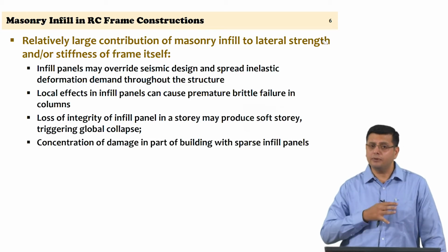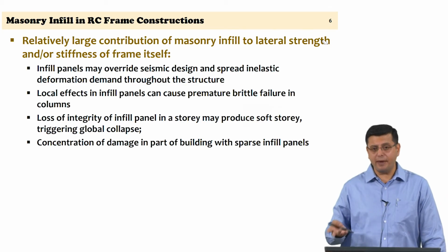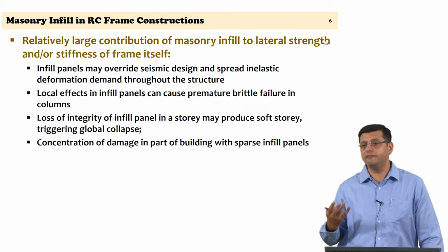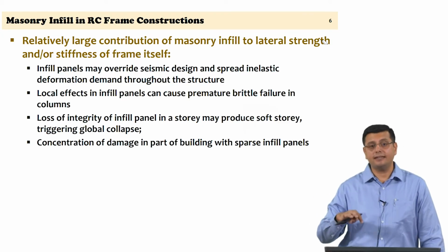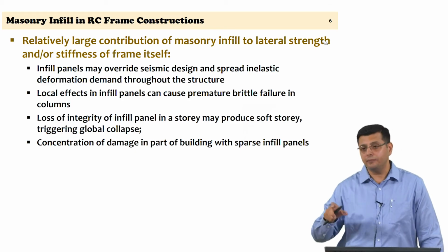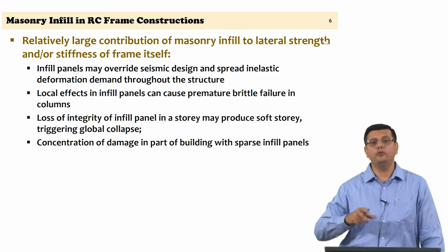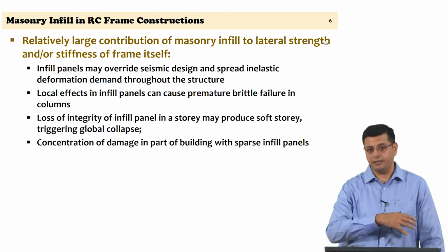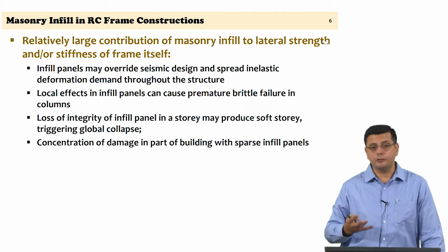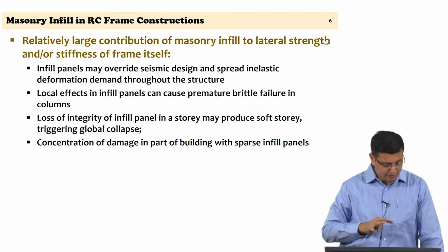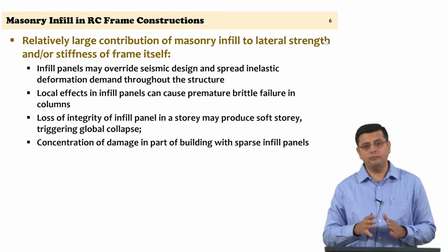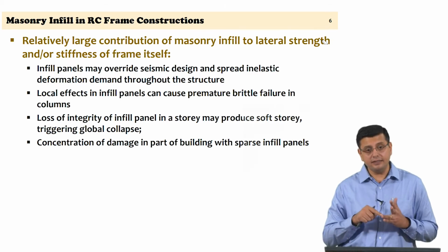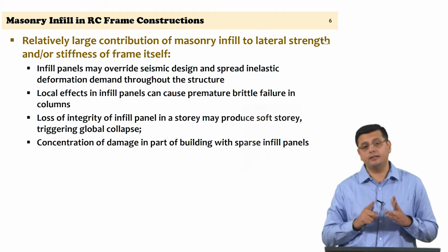Again, if you are designing the moment resisting frame as a bare frame and have not considered a non-uniform distribution of the infill panels in different parts of the building, that has an effect in terms of additional torsional forces coming in, and you can have concentration of damage in the flexible side of the structure where infill panels are sparse. So, this is a problem because of non-consideration of the interaction effects in seismically designed moment resisting frames considered as bare frames.